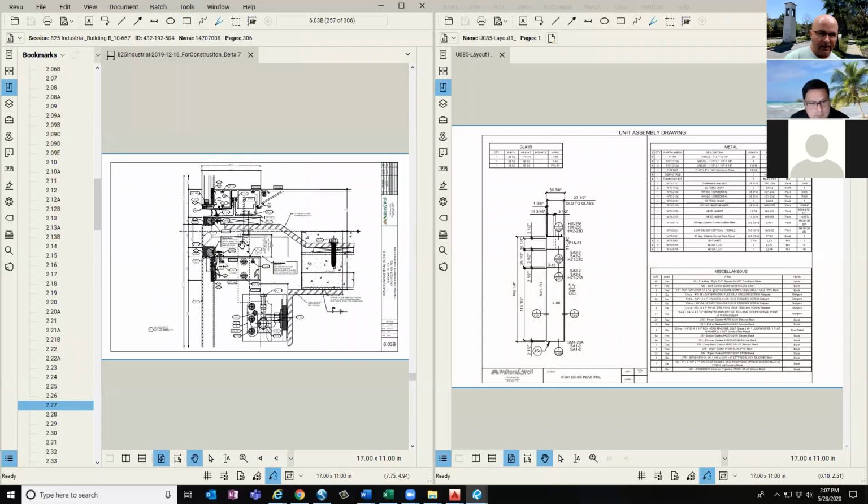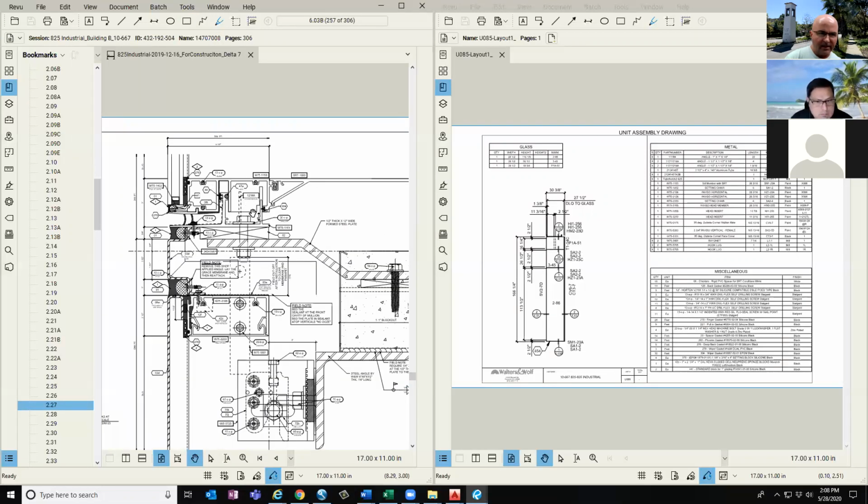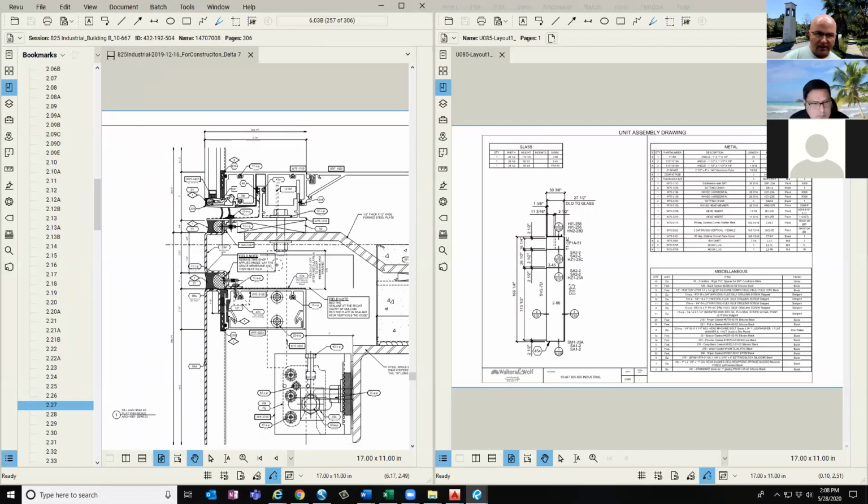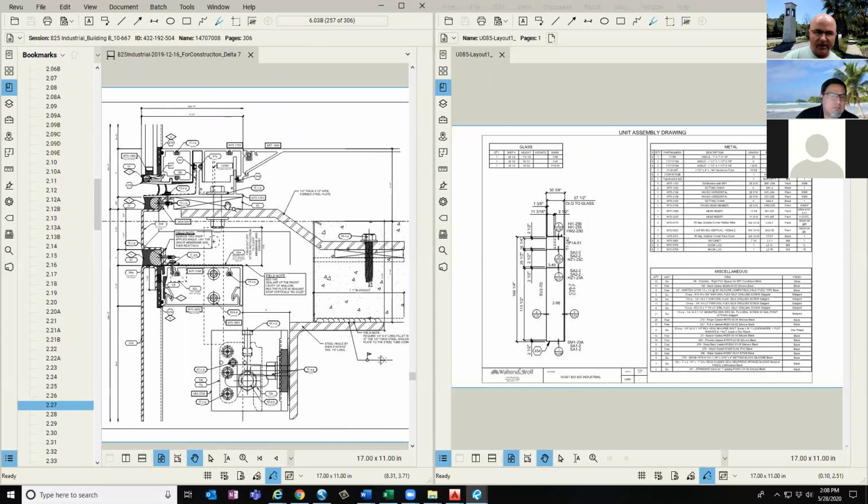So if I navigate to here, I see right away that I've got a sill track. Since it's the bottom of the unit, I know that it's not this lower portion I'm looking at, it's this portion here. And it's attached to a sill track, but I'm seeing that there's something unusual happening here. It's not attached to a curb or stud framing. It's got this offset steel plate. So that's going to prompt some things for me to think about as I'm continuing this process.